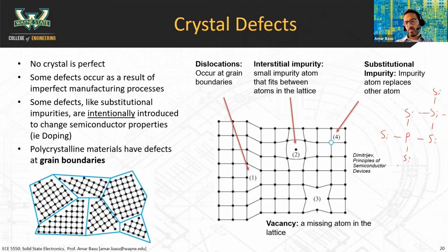So phosphorus, we're going to talk about doping a lot in the third module. So I'm not going to get into all the details of this, but when you switch out silicon, which is a column 4 element, with phosphorus, which is a column 5 element, it brings in an additional electron. So this additional electron, it turns out, is free to move about the lattice, and it creates an electron in the material, and that creates a more conductive material. That's called doping. That's doping N-type.